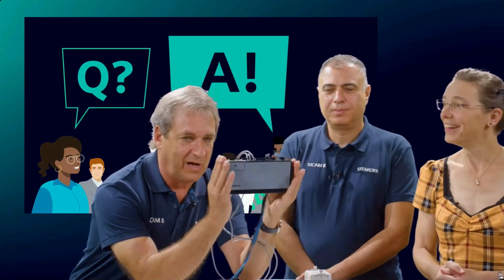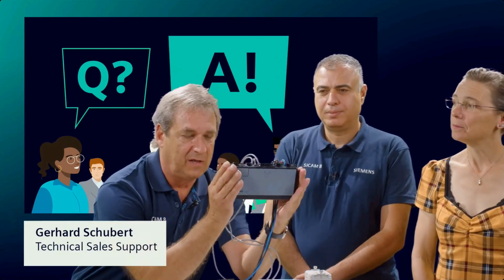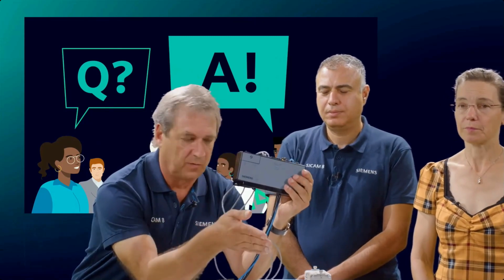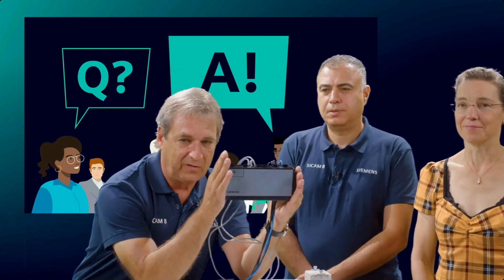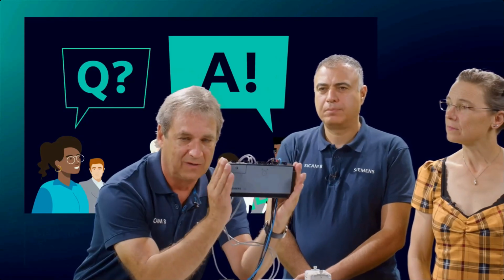And the task of it is, imagine that you have a cut in the power supply. The transformer feeder, for instance, trips. Many customers are interested in getting the last valid values before and after the trip. And therefore, we have this capacitor, which is able to power at least this device for 1 minute. That's quite some time, right? It's enough time for this before and after.